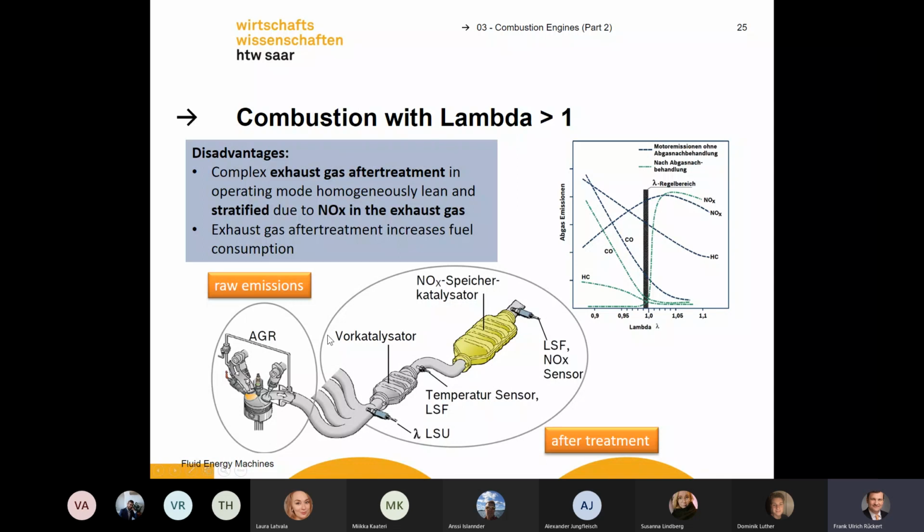Okay, and here you can see an exhaust gas treatment system. It's for cleaning. It's a nitrogen oxide catalyst. You have here a lambda sensor. You can have exhaust gas recirculation here to clean. You can recirculate the gas from the cylinder to clean it. Here's your manifold. You have your catalyst, and you can also use NOx sensors to control your catalyst.